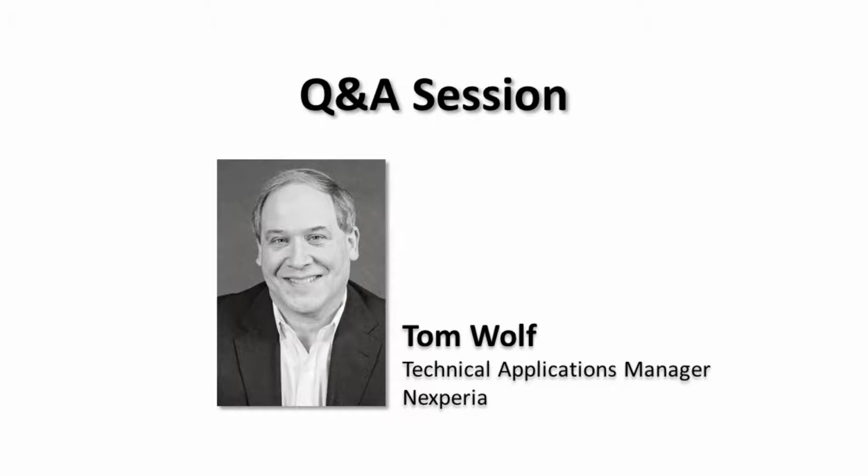Okay. Does the application handbook get into the power RF applications? RF, I assume, means radio frequency parts. These parts are not really designed for those very high frequencies. So no, not in particular. The handbook certainly does talk about the motor control frequencies, 20 to 30 kilohertz. It also deals with power supply applications, which are hundreds of kilohertz or up to a megahertz. RF, I would safely say, starts above that frequency, so probably not. So yeah, we can support up to the megahertz range with them, and that information is in the applications guide.